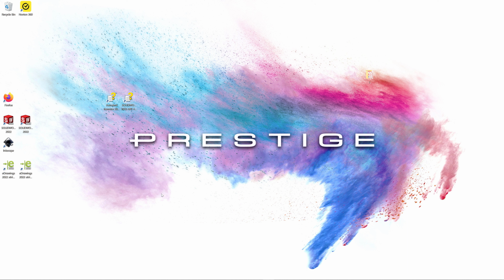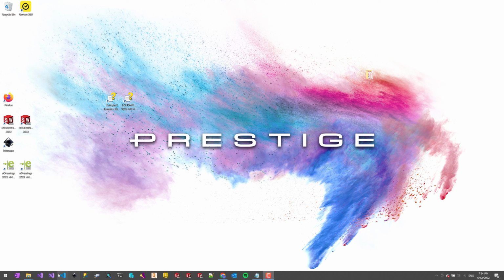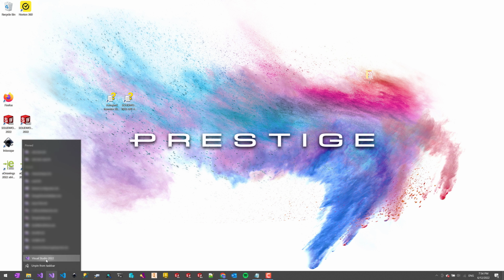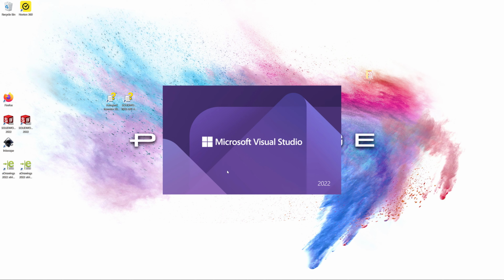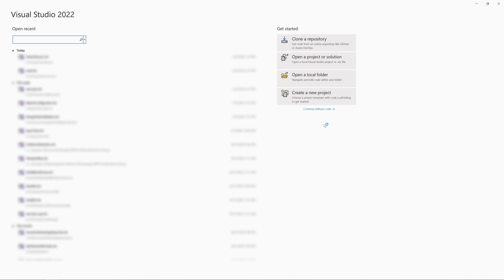In order to properly register a SOLIDWORKS add-in, it is required to have administrative privileges to do so. So, to simplify the debugging process, I recommend running your Visual Studio as administrator, so you can debug your add-in directly from Visual Studio. For that, you just need to right mouse button click on the Visual Studio icon and select Run as Administrator.